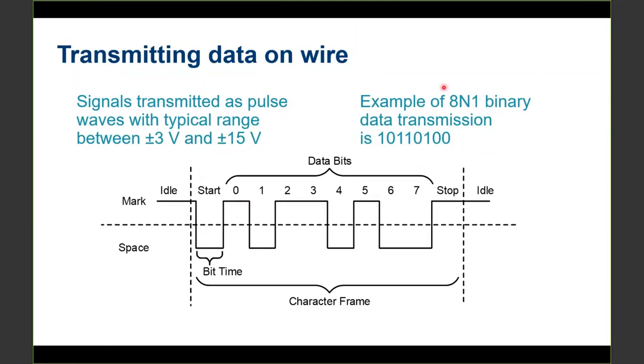If you wanted to get this square wave and look at it, let's say this is a typical transmitted frame from one device to the other. One question I would normally ask is, okay, this is a transmit frame from a typical 232 DTE device. Your pin out for the DTE device has your transmit data on pin 3.